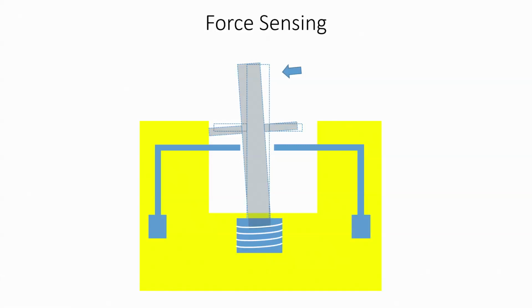If the force is in this particular direction, which is shown here, again you will see the change in the spacing between the electrodes, and you can see the change in the capacitance. But this is only one way. There can be a capacitive force sensor, a piezoresistive force sensor, a cantilever, there can be strain gauges. There is unlimited design for force sensing.